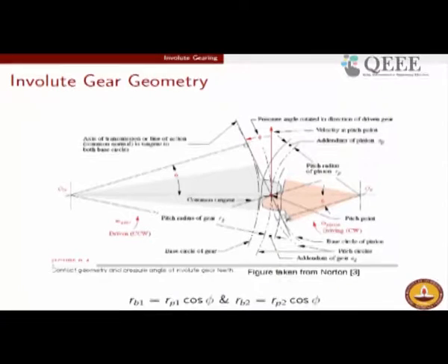Fortunately for involute gearing, the common normal does not change during the course of engagement. From the perspective of transmission of forces, the normal force is the major force being transmitted, even if there is no friction in this process. That is why it is called a positive drive. It does not depend upon any friction aspects for this mechanism to work. It does not work on the no slip condition principles.